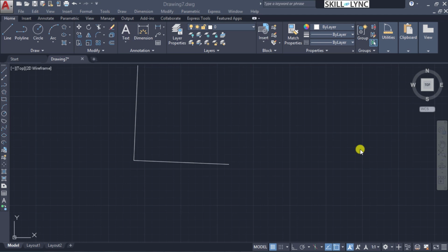That is, suppose you are assembling a shaft onto a hole, then the edges of the shaft will have to be chamfered so that it will get guided into the hole easily. And in cases of interference fit components and all those things, the chamfer is a key mechanical design element. So let's look into how chamfer is executed in AutoCAD.